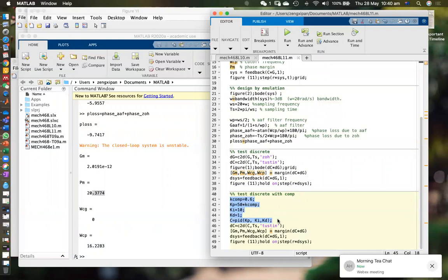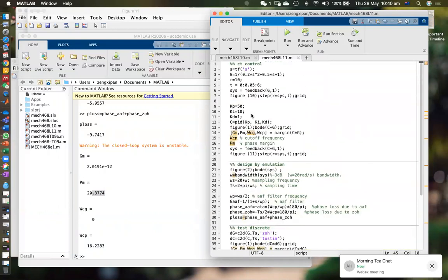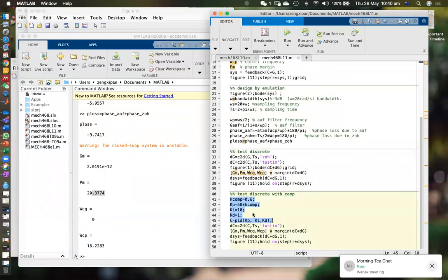We design another continuous controller. So this is the original controller. Because it's KP, if you muck around a little bit, KP is the reason causing the system to get unstable. If we reduce the KP, the system will be slightly slower but more stable. So I keep the KI and KD unchanged. Just make the KP, I'll put a ratio there because I don't know what I'm after. Okay, so I made KP 0.9, just slightly smaller, and see what happened.